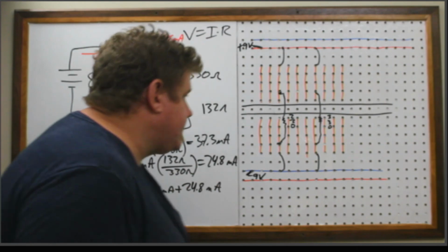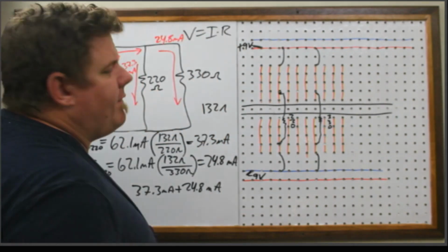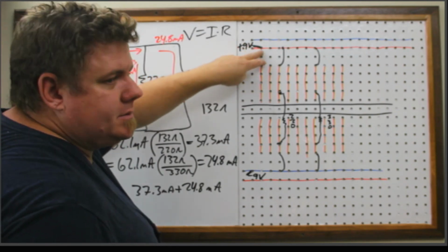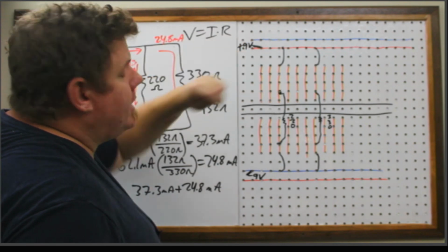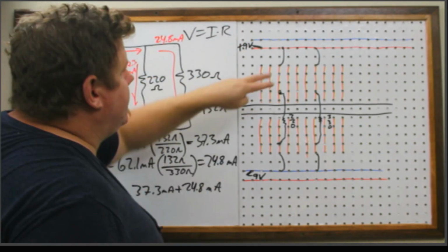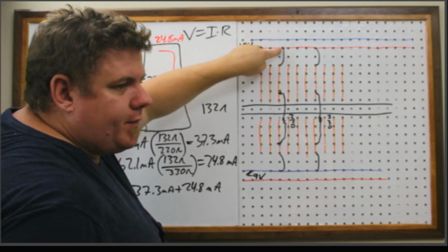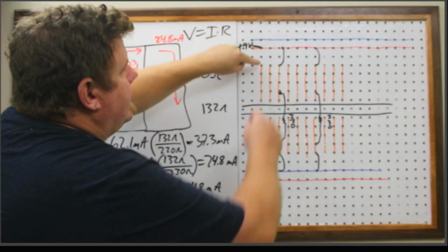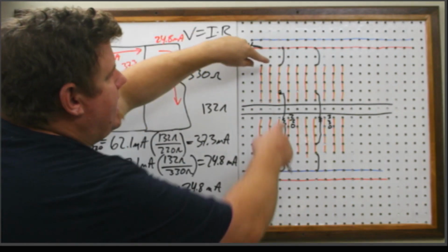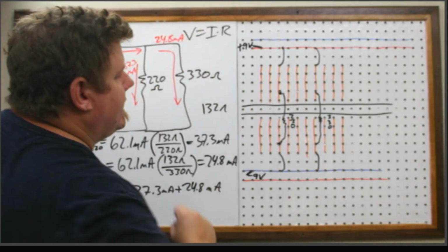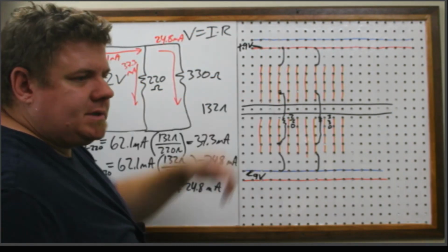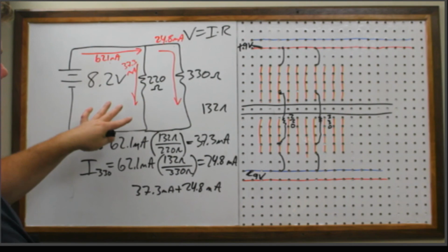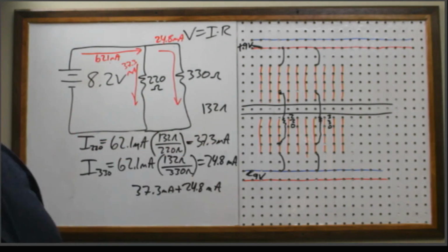So I'm going to be inserting my ammeter. If I want the total circuit current, I would have to do it before the 9-volt lead and this rail. Okay, and I'm going to measure it up there. Then I'm going to do the individual branch currents, and so to do that, I can pull from right here and undo that, and then place it in between. I can pull this here, and then have it in between that wire and this terminal here. So what I'm doing is I'm setting this up so it's easy to make a good ammeter measurement. Okay, I'm going to keep these measurements up here, and I'm going to go ahead and construct this circuit.